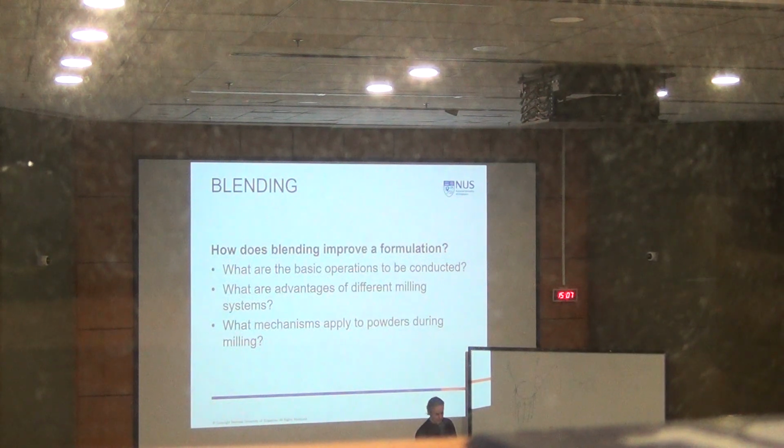The effect that you have there is mostly that in the beginning you have magnesium stearate also in particle form, and over time, when you mix too long, these very often break and then coat the bigger particles, which means the adhesion forces between other particles, that you usually would like to have very low, are growing. So the bigger particles are just pinned together by broken magnesium stearate particles.